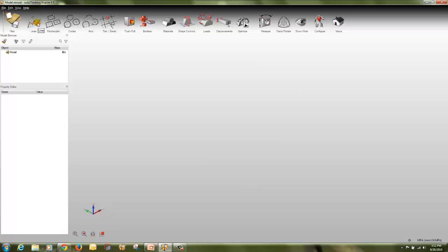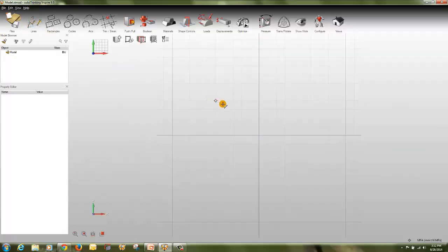Then the line between 2 points. So from one point to another, this is the line. If you want some particular distance, like 150 mm, or 20 mm, you can have that. Right click, you can also change the distance from here, and the direction from here. You can just move this point, and you can also move this point.